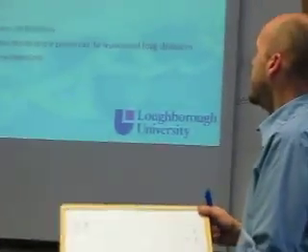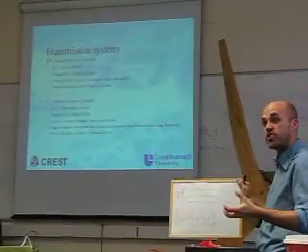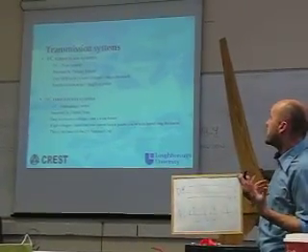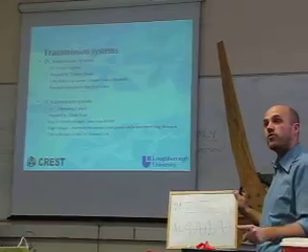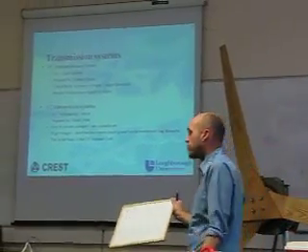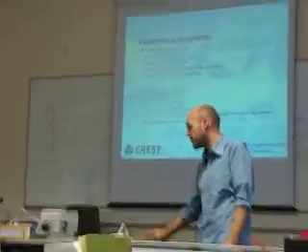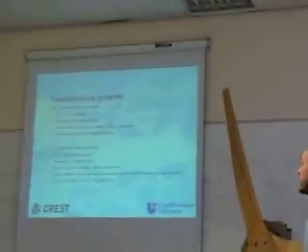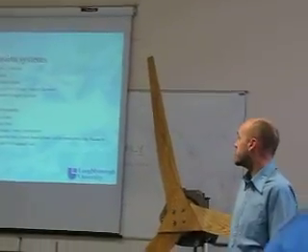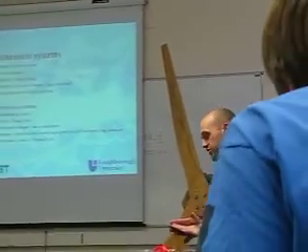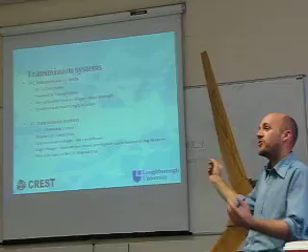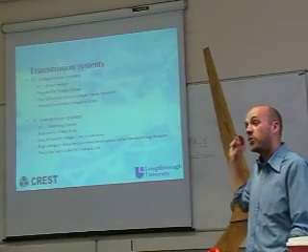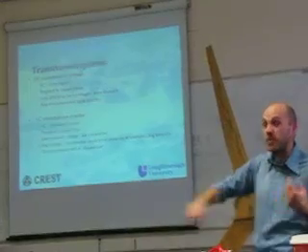Generally about that. Now, what Tesla saw was that you can very easily generate AC power from a rotating generator. And he also knew that you could convert AC from one voltage to another using a transformer. A transformer is very robust, relatively easy to build technology, and they knew how to do it. So he proposed using alternating current, where you can convert your voltages to transmit them at a very high voltage, therefore the current is very low, therefore the resistive losses are very low, therefore your wires can be much smaller, much cheaper, and you can transmit miles and miles and miles.